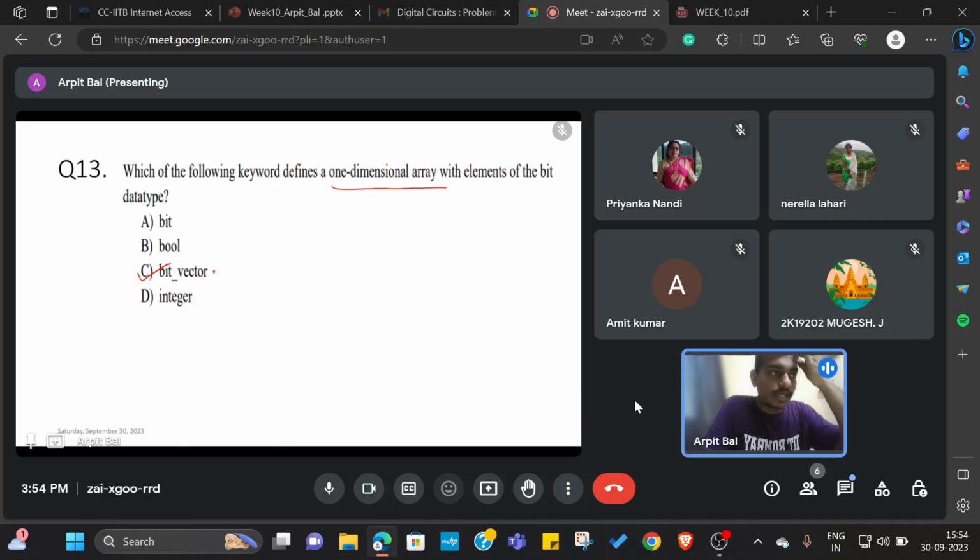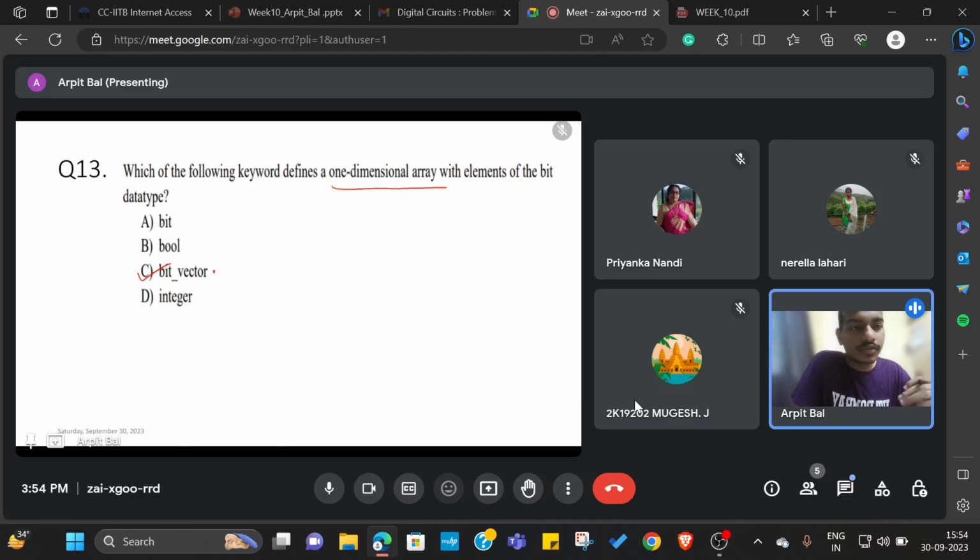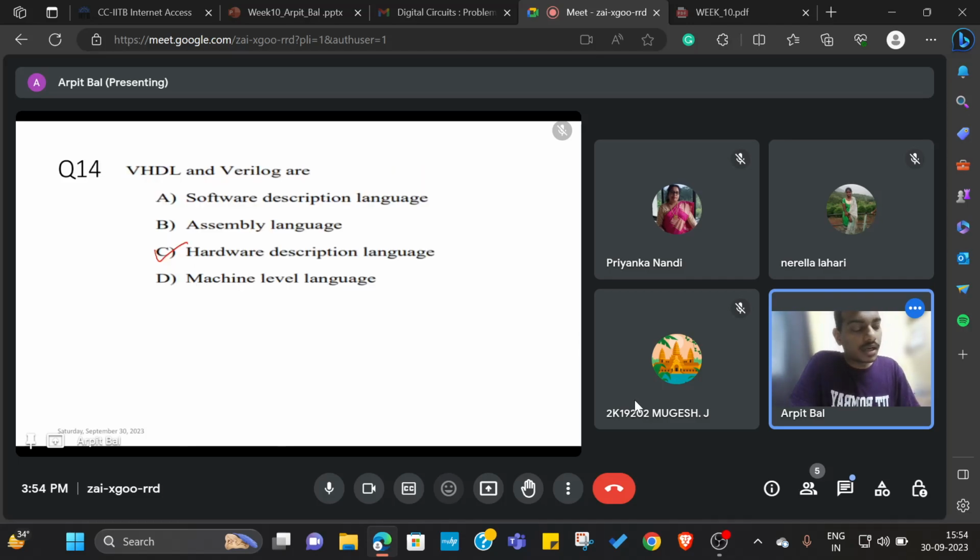This is a very sensitive part, the data types that you are going to use. It is possible that the hardware you are trying to infer is not going to be generated only because there is a data type mismatch. So it means you should know your tools very well before you go to an actual war, right? So that is related to data types.